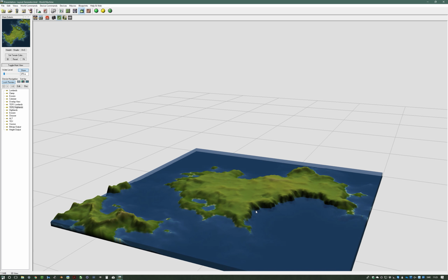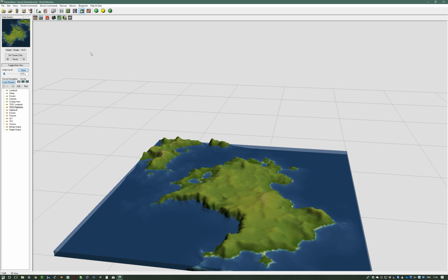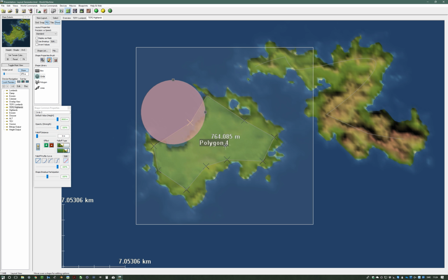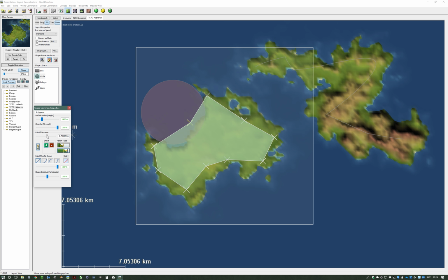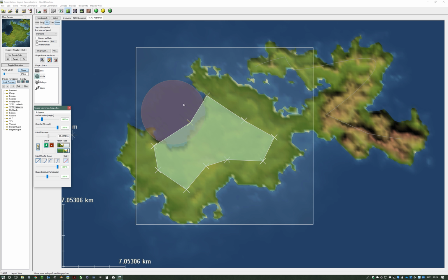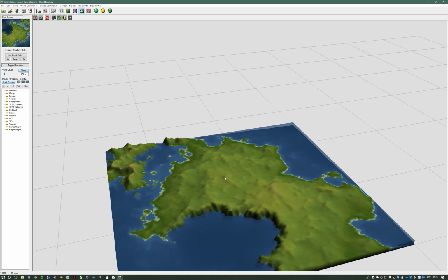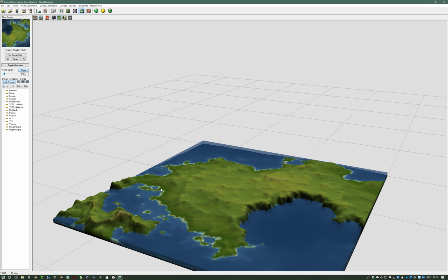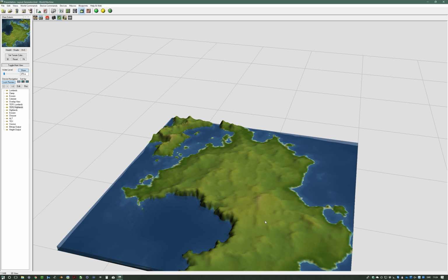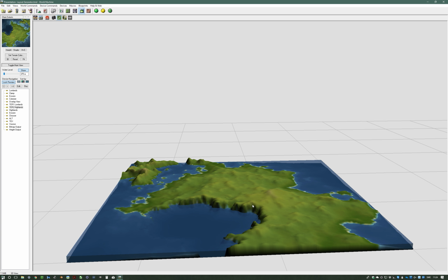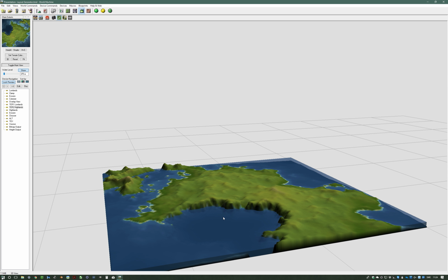So here, if I use the combination, if I take the polygon again and I increase the fall off on the polygon, but I keep the fall off at 0 on the circle here, that means that now I created a varied coastline with smooth beach-like coastlines on most of it, and this part here has very harsh cliffs, and it's also deep.